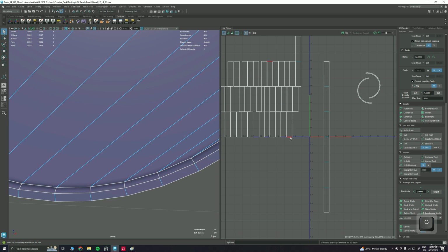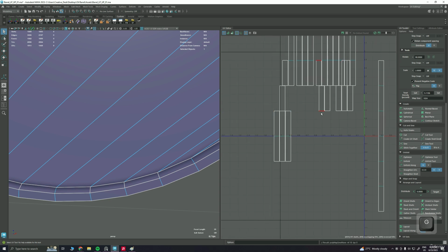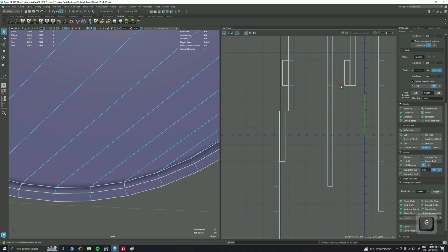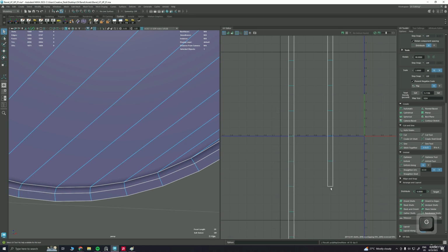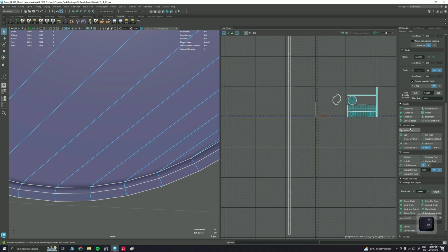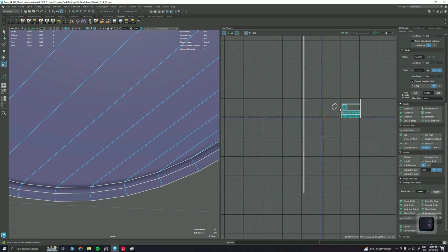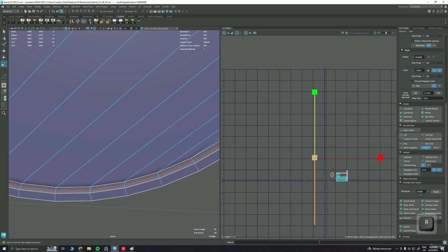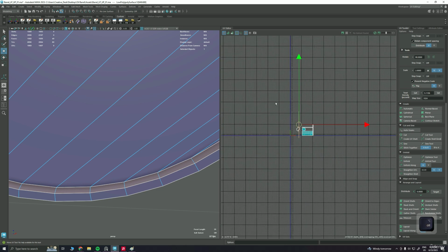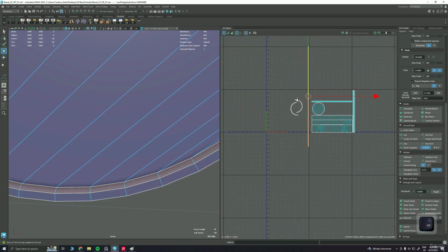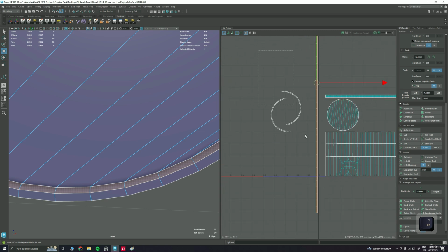Select an edge and press G to repeat the command. So the UVs will start stitching themselves to the respective edge. Like this. Done. So you can rescale this and bring it close to the UV tile 0 to 1 space so you don't miss out. So let's do the same for this too.